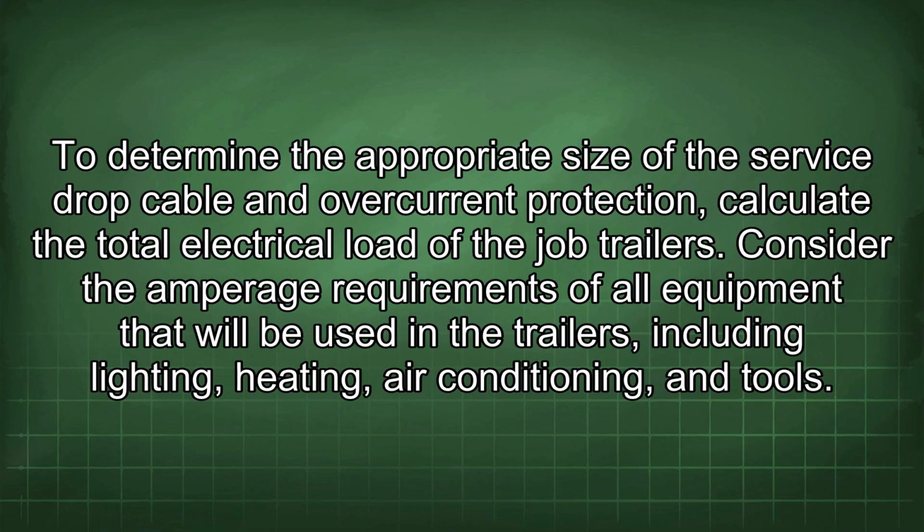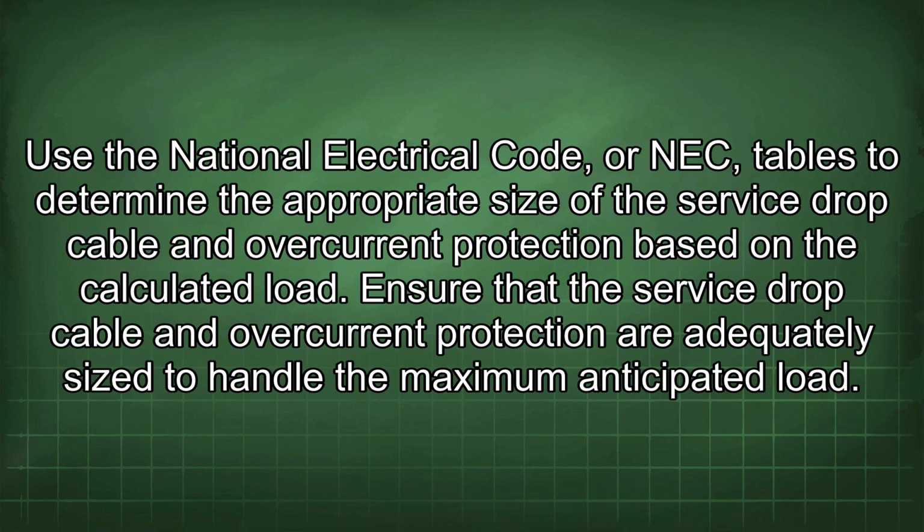To determine the appropriate size of the service drop cable and overcurrent protection, calculate the total electrical load of the job trailers. Consider the amperage requirements of all equipment that will be used in the trailers, including lighting, heating, air conditioning, and tools. Use the National Electrical Code, or NEC, tables to determine the appropriate size of the service drop cable and overcurrent protection based on the calculated load. Ensure that the service drop cable and overcurrent protection are adequately sized to handle the maximum anticipated load.